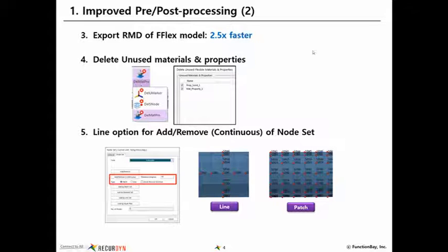That's an old feature that I use quite a bit. When you've been making a lot of edits to your model, deleting bodies, including new bodies, deleting joints, including new things, a lot of times you end up with a lot of unused markers, and so that's a quick feature to delete all those unused markers.